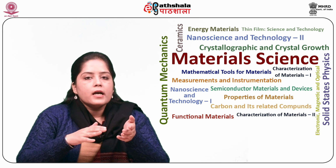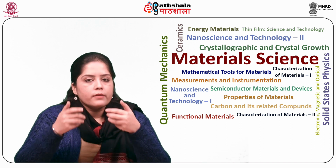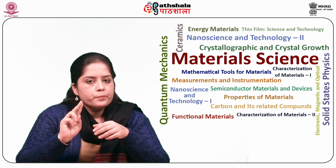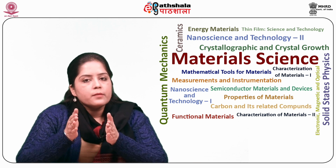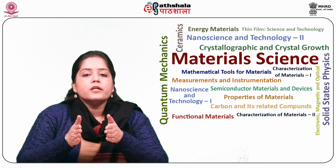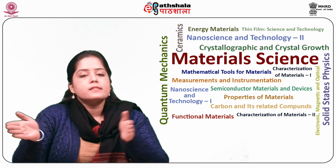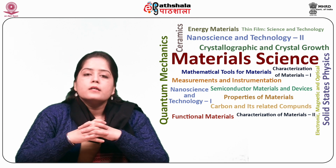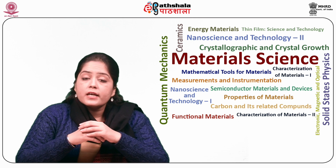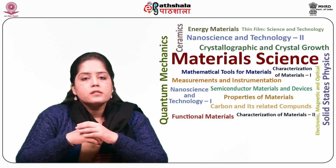Electronic elements from semiconducting nanowires can be summarized as: first, chemically dope the nanowire with appropriate species in order to produce p type or n type nanowires. A PN junction needs to be created. PN junctions have been prepared in two ways: physically crossing a p type nanowire over the n type nanowire. Secondly, chemically dope a single nanowire with different dopants along its length. So, with the PN junction prepared from nanowires, logic gates can be fabricated, which include AND, OR, and NOT gates.